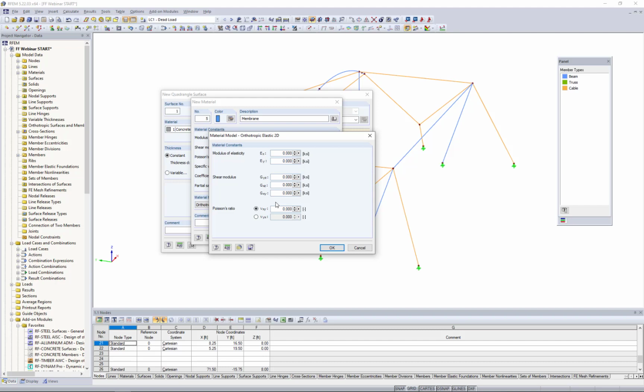So for today, let's say that we've referred to our manufacturer and he's given us the stiffness in the X direction as 1 gigapascal. But notice that my units here are KSI. So just a nice little trick within the program. If you don't want to manually convert gigapascal to KSI, what I can do here is type in 1.0. Then I can manually type in capital G, capital P, lowercase a for gigapascals. Notice when I click in the next cell, the stiffness is automatically converted to KSI, 145.04.